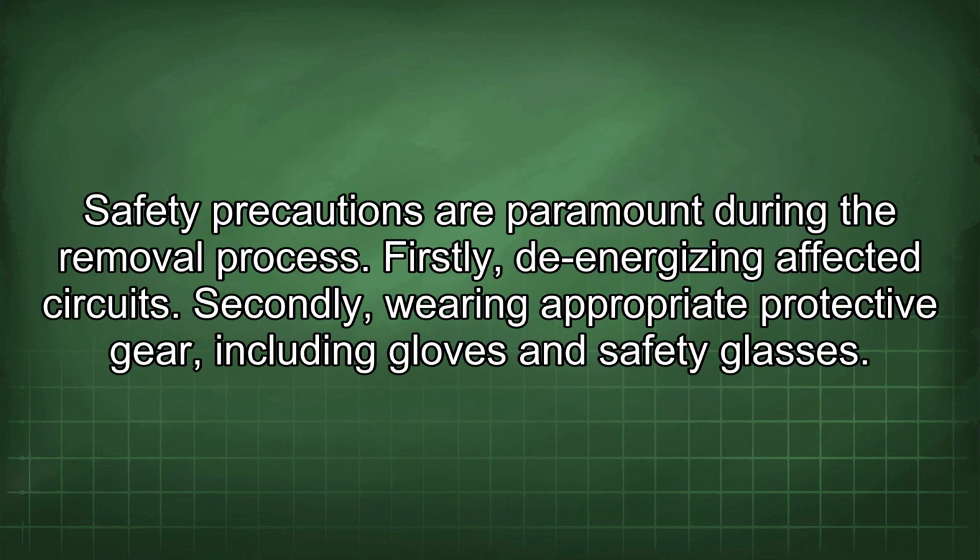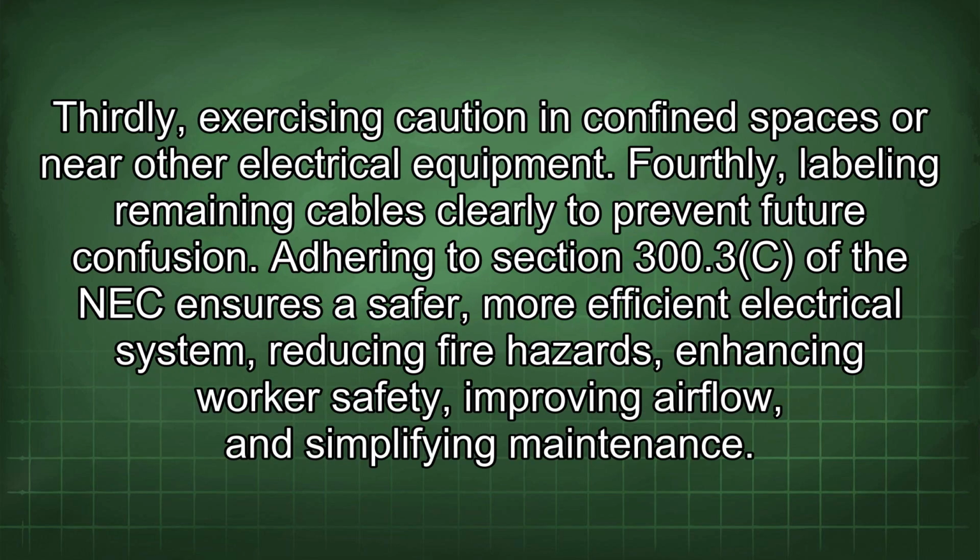Safety precautions are paramount during the removal process. Firstly, de-energizing affected circuits. Secondly, wearing appropriate protective gear, including gloves and safety glasses. Thirdly, exercising caution in confined spaces or near other electrical equipment. Fourthly, labeling remaining cables clearly to prevent future confusion.